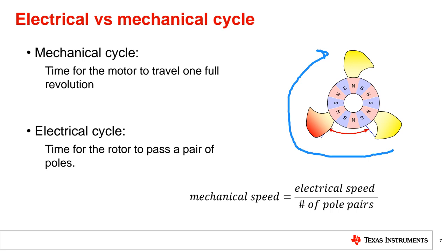The reason why electrical cycles are significant is that in some methods of rotor position tracking, rotor position is detected in terms of electrical cycle. If you want to design a control approach for your brushless DC motor, you need to check the electrical cycle. Every time we are using the electrical cycle in control techniques. What are the control techniques? Six-step trapezoidal control, sensorless control, also another one, etc.